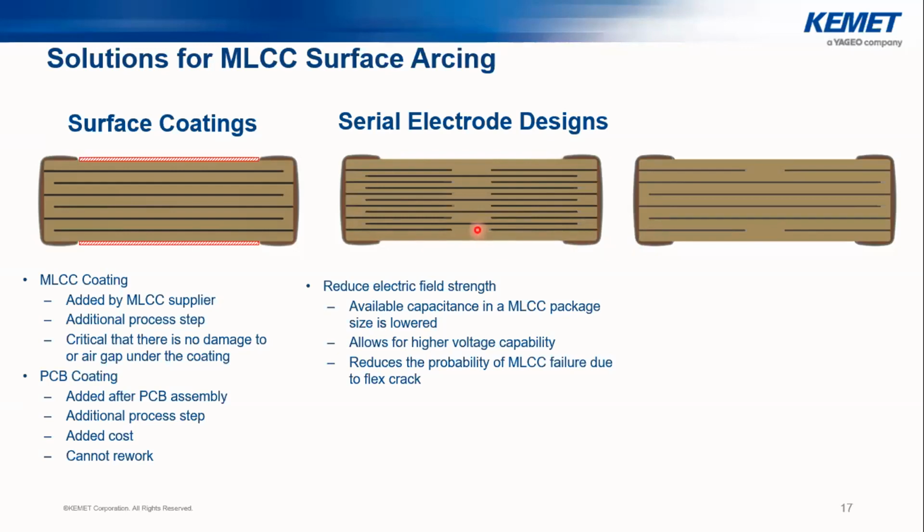But it allows for higher voltage capability and even reduces the probability of failure due to flex cracks. For example, if we have a crack on one side, we still keep the other side safe and we don't lose the capacitance.